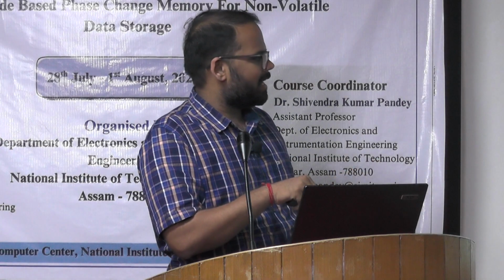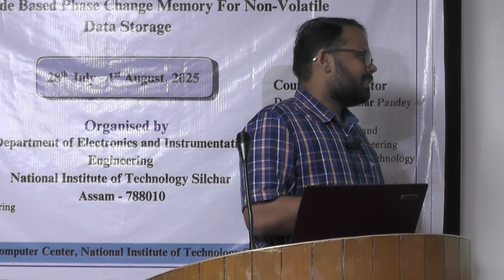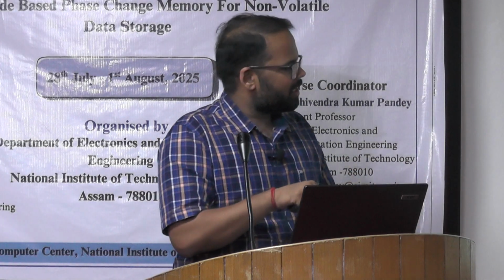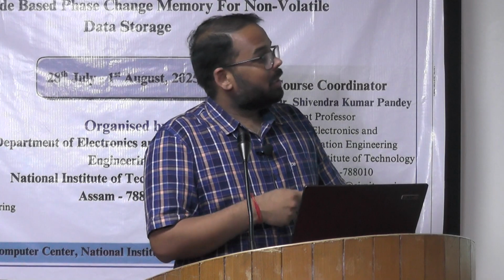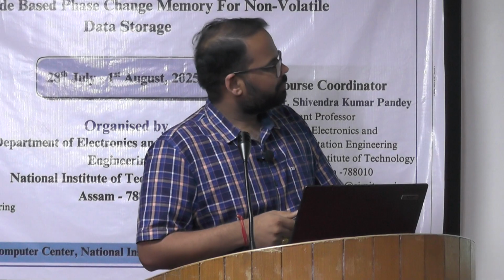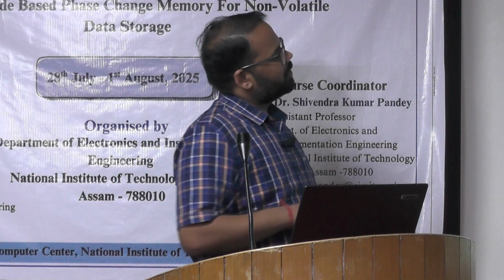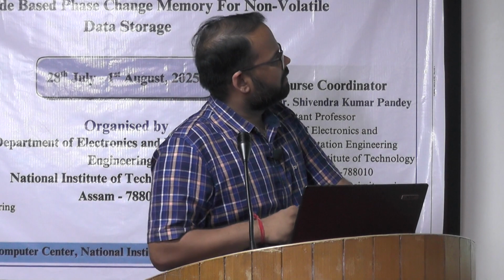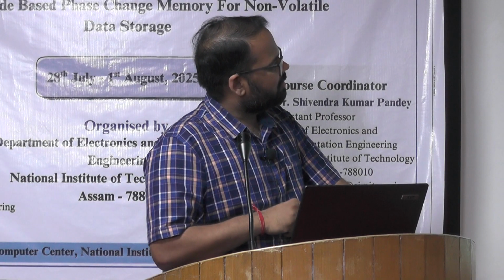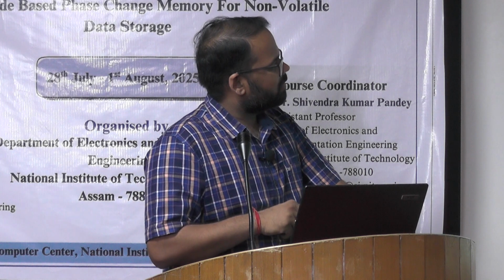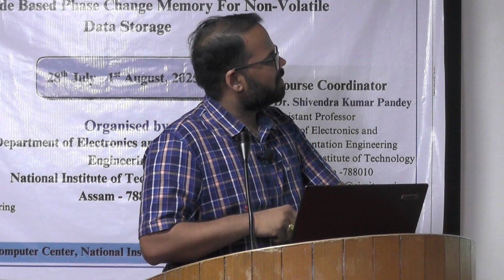So this is a kind of custom built switching network and data acquisition setup which is reported in this work, where with respect to that SMU you can change the terminal and identify the resistance value. This is the pictorial view of this switching board, where this kind of relay is connected with transistors, so it operates through this control signal.